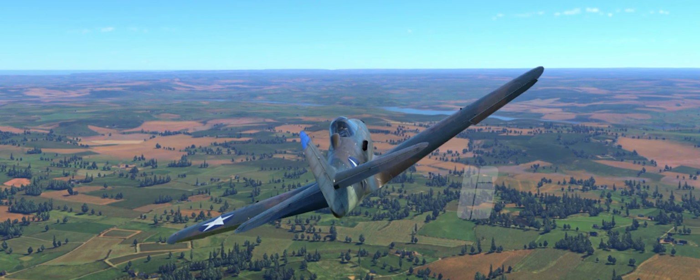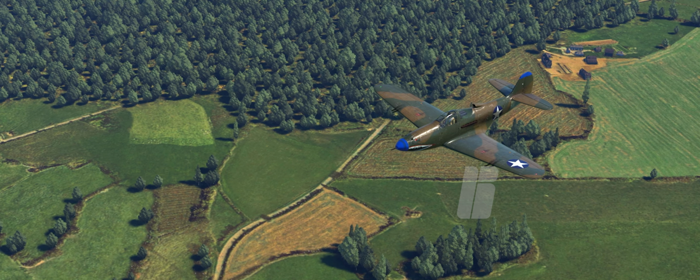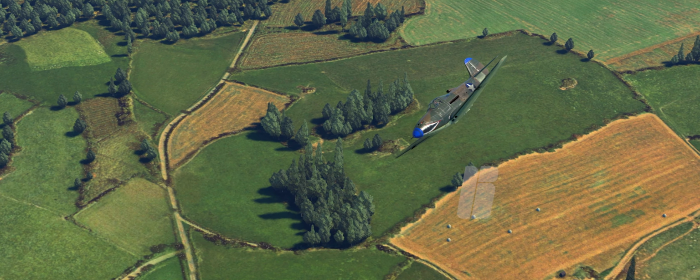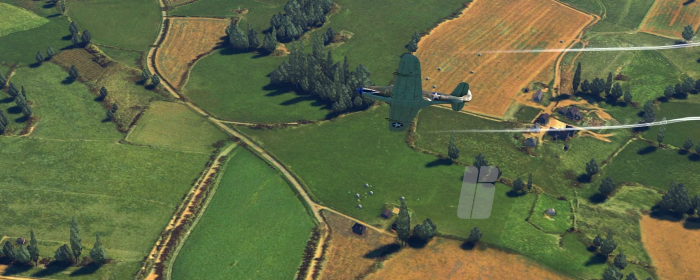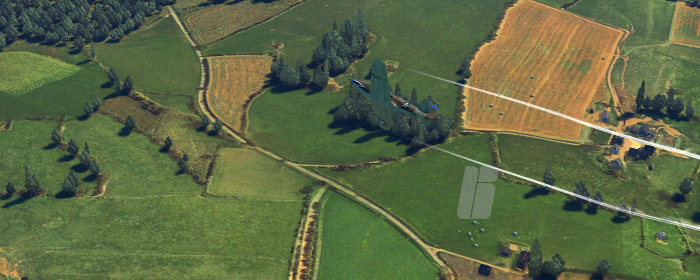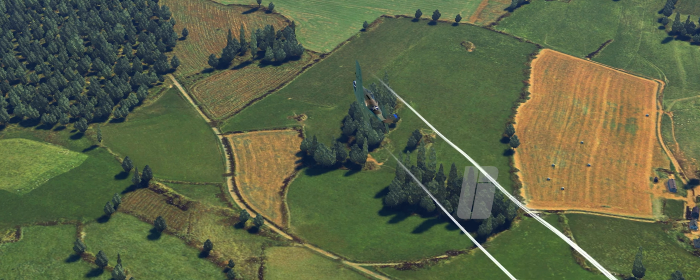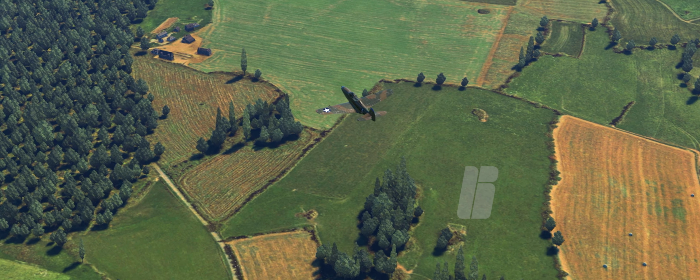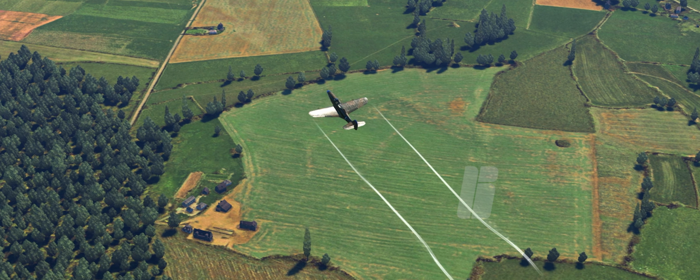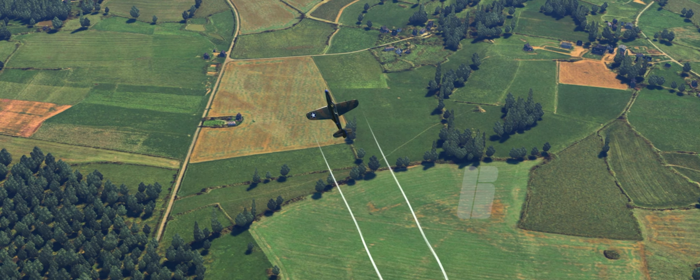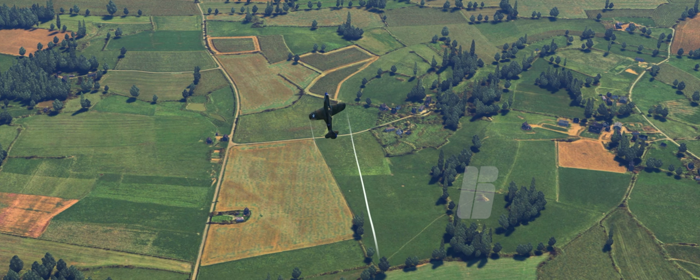Now, how do all three work together? In real life, pilots rarely use just one control surface. Turning an aircraft properly requires coordinated use of all three controls: the ailerons to roll the aircraft into the turn, the elevator to maintain lift during the bank, and the rudder to keep the turn coordinated. This combination ensures that the aircraft turns smoothly and efficiently.